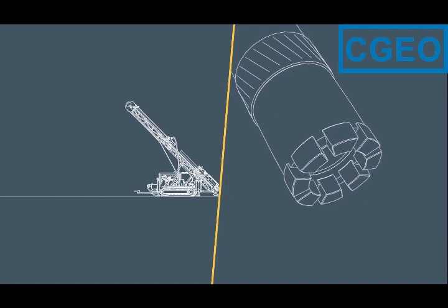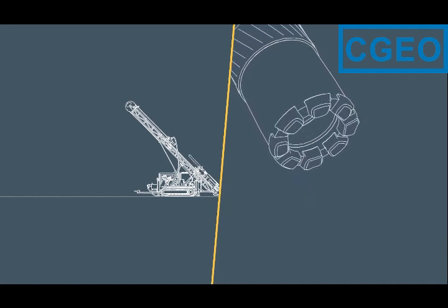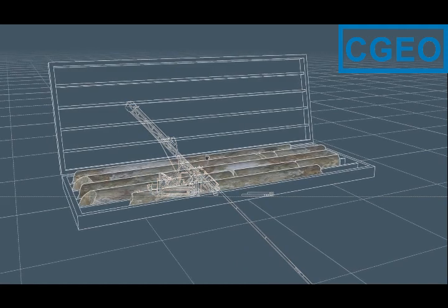When the drill bit is worn out, the whole drill string has to be taken out of the drill hole, regardless of drilling method. Therefore, choosing the right drill bit for the formation is extremely important for high productivity.